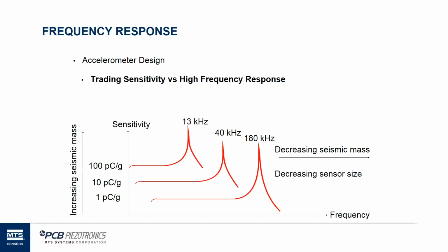specific, because what we'll find is on structures that operate at very high frequencies, the acceleration levels are also very high frequency. They're also very high level vibrations. We want to use on those structures, they're usually very lightweight structures with high frequency activity. It works out to our advantage that we have a lightweight sensor for a high frequency application on a very low mass type structure and a very high resonant frequency of the accelerometer. Those things kind of go together, right?